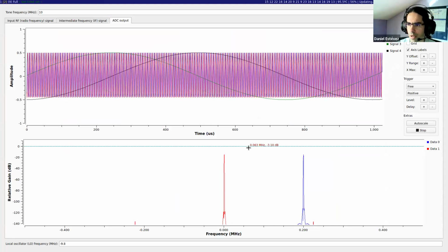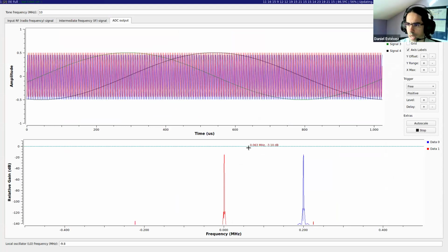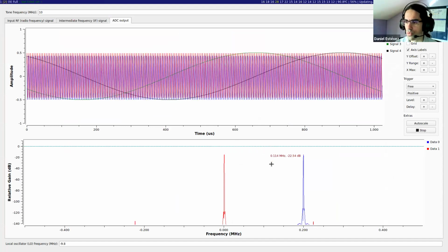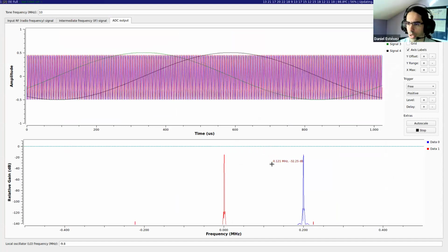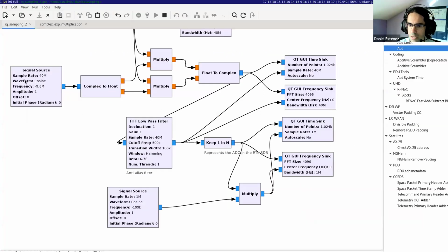If it's the first time you see it, it might be a bit confusing. It is really something you need to think about and internalize these concepts. But really the bottom line here is when we have complex signals, it is easier to move them in frequency. And so many SDRs are built in such a way that they give us complex signals, where complex really means this thing.